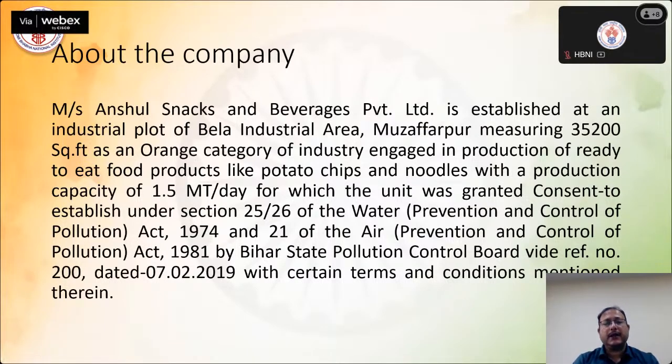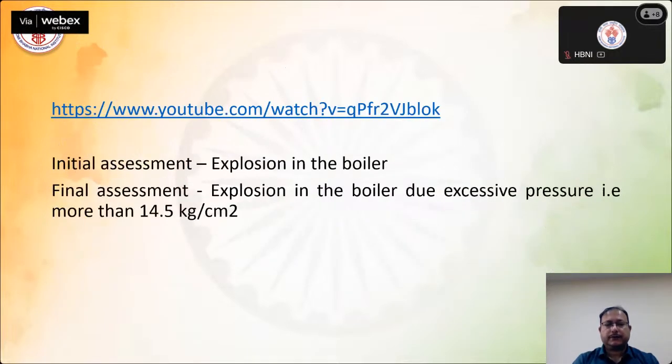So if you look at the legal part, they are legally bound by certain acts through which they received an intimation to start their production. The initial assessment was that the explosion was again in the boiler. The final assessment was explosion in the boiler due to excessive pressure, that is, more than 14.5 kg per square centimeter.